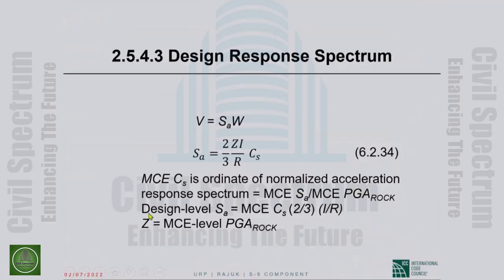Now, design level S sub A is the MCE level C sub S, this quantity, multiplied by 2/3 to go down from maximum considered earthquake to design level.